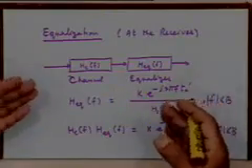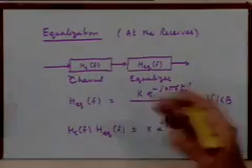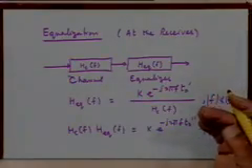For example, a wireless channel in which there are lots of reflections from various objects in the propagation path, and these objects keep moving or you keep moving, right? Obviously it's a linear characteristic, but it's not time invariant. It's a linear time varying characteristic. Then of course this equalization business becomes even more difficult, because not only do you not know the channel, it keeps varying with time, right?